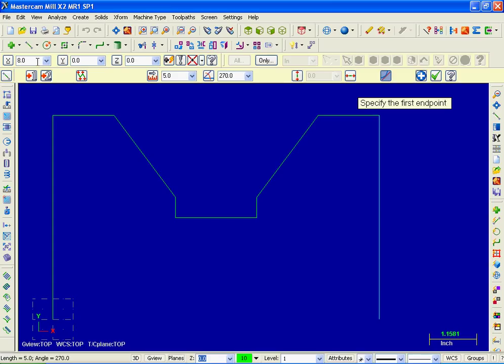Wonderful. Last line, line 10. So, going to click on this point, click in the X value. So, our final resting place is 0 in X. Hit the Tab key. It's 0 in Y. Hit the Tab key one more time. Z0 here, and hit the Tab key. Everything looks great. I'm going to move up to the ribbon bar and click on the Apply button. Everything looks fantastic. Let's click on OK. We're done here.